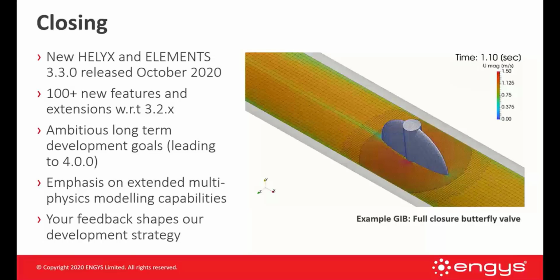Let's see. One other question talking about coupled solvers is, what's the source of the coupled solver speed increase between versions? From my understanding, the real difference is there's improvements in the algorithm from the 3.2 code base of coupled up to 3.3. So there's improvements in the algorithm. There's also memory management improvements. So there's fewer cache misses, so it's more efficient with its memory management. And then the last one was the linear system solver improvements in terms of the multi-grid solver that comes with it. So from my understanding, that is the major area of improvement, which actually gave that 20% improvement from the last one.